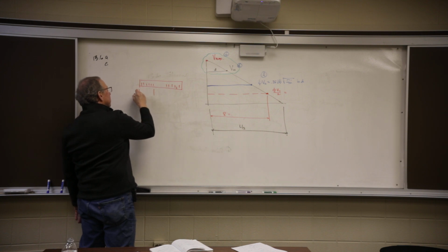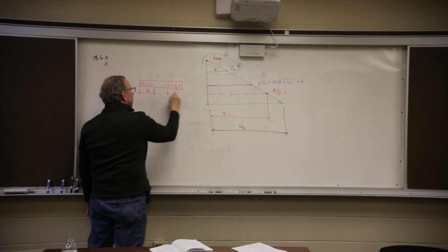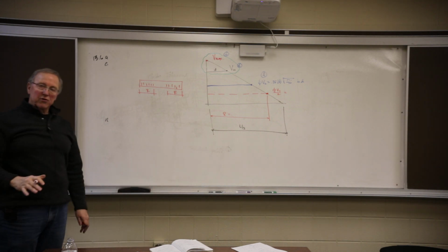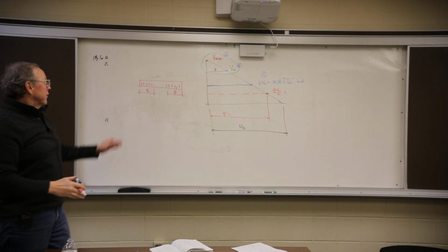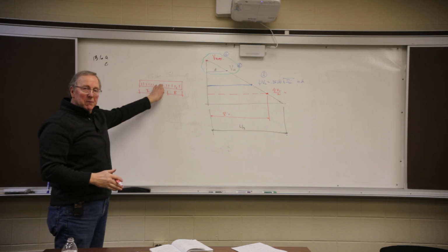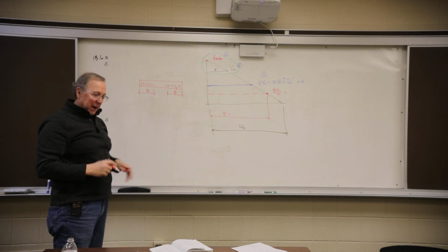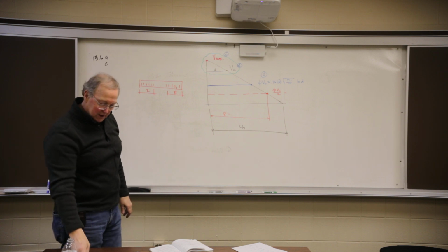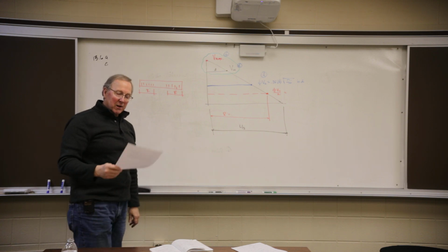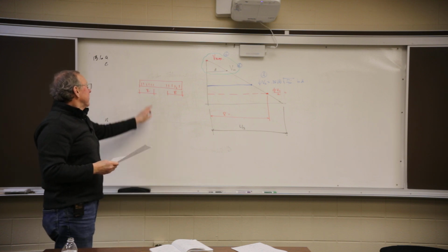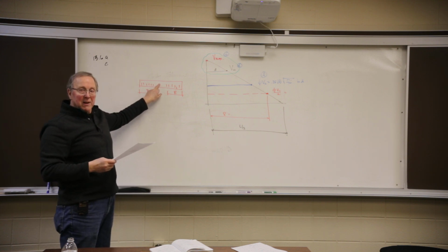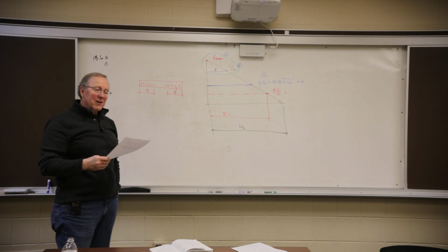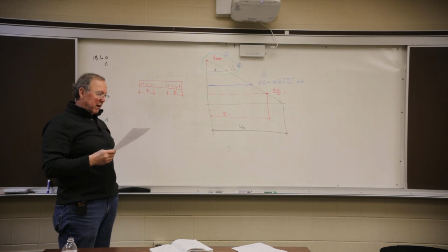If I go this way R and this way R, that's the limits of the positions of the stirrups. There may be a gap in the middle. It usually is. Sometimes we put them in to facilitate installation of longitudinal bars, but sometimes we don't. So if you don't see stirrups in the middle, don't be concerned. If you don't see stirrups at the end, that's a red flag. You should know that they need to be there.